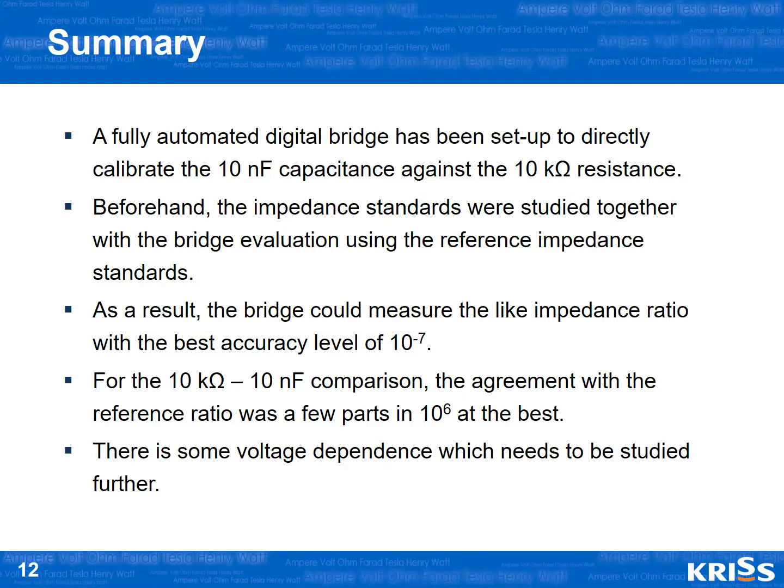The impedance standards were stable, and the fully digital bridge could measure the 1-to-1 or 10-to-1 capacitance to capacitance and resistance to resistance ratio with an accuracy at the 10 to the minus 7 level at the best.